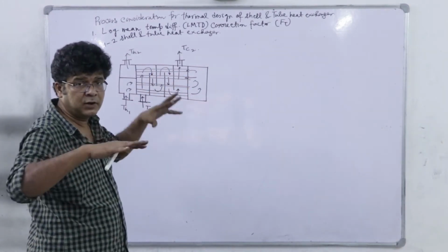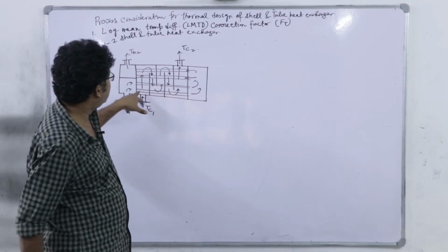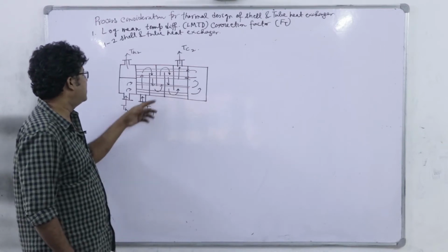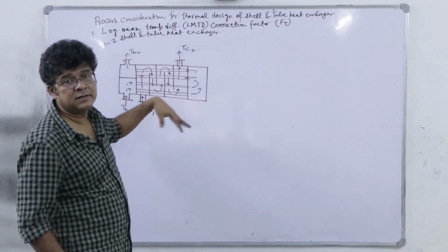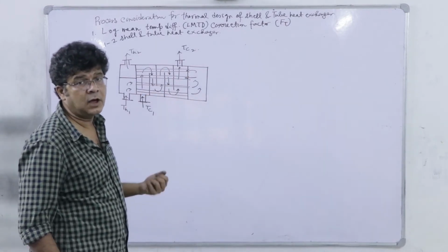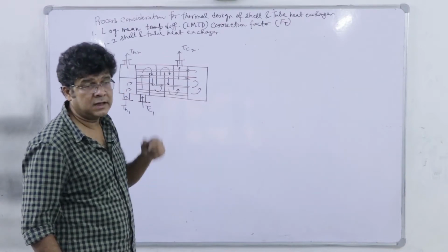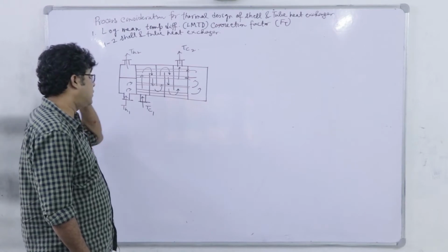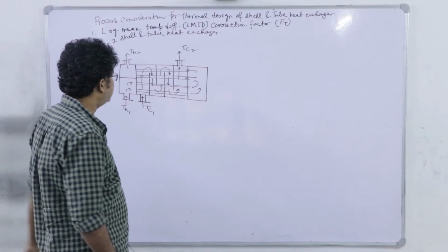Because if both are in the liquid phase, then generally we deliver the hot fluid through the tube side, because if we deliver it in the shell side, there are chances that we will have a loss of thermal energy and we cannot optimally utilize the enthalpy in heating up the other stream. So that's why the hot fluid is commonly recommended to be delivered to the tube side.